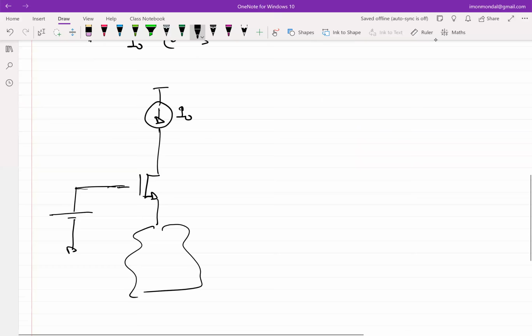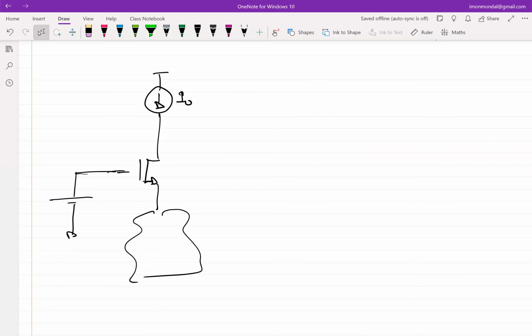So before we get into applying anything at the source, we argue with ourselves: what is the drain voltage, and from there, how do I get a sense of in which direction I need to move, right? The sense of feedback should be right in order to figure out whether negative feedback is working or not. So now let's argue. You will have drain current ID.